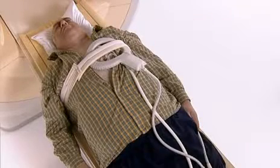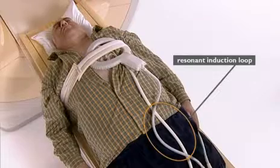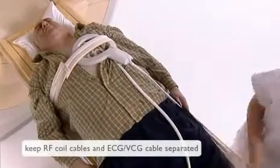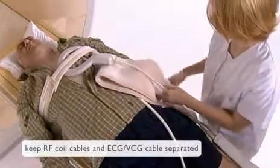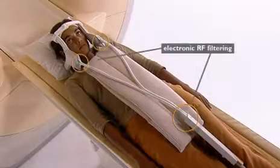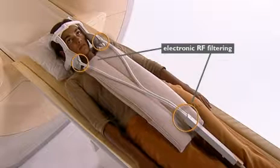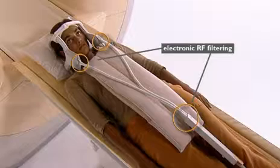Unfortunately, apart from the receive coils, resonant induction loops can be created accidentally. These may act as additional unwanted RF antennas. Electronic RF filtering is applied to prevent cables and other components of RF receive coils becoming part of potential unwanted antennas.